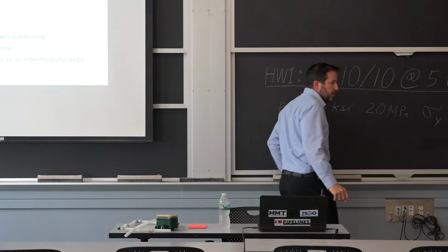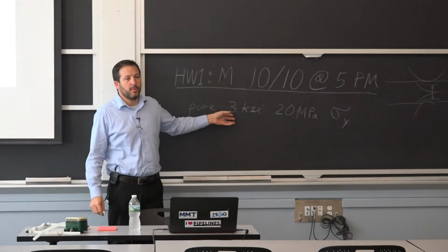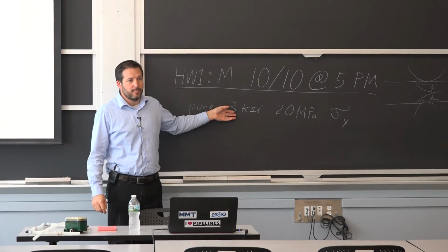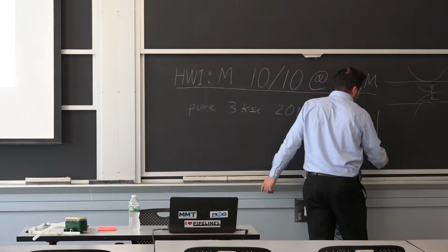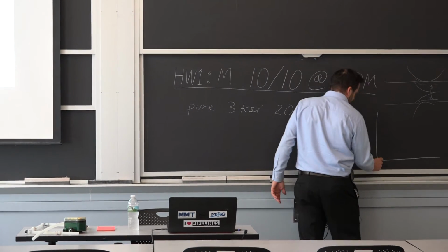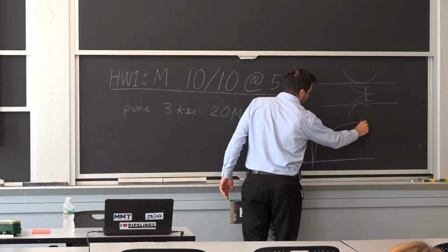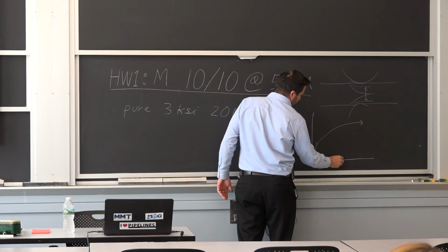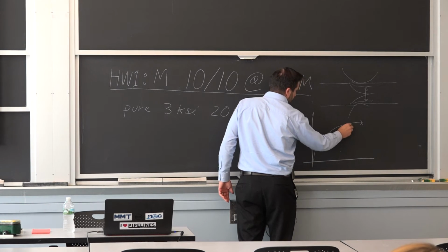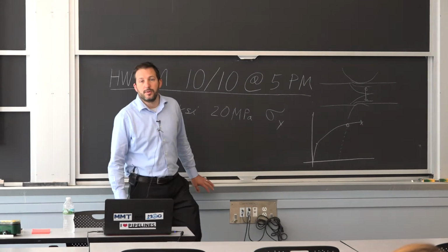Is that enough? No, because there's a lot of tension in the power line. So you try to double or triple that amount, but what it means on the stress strain curve, because you're doing it at ambient temperature, is your aluminum typically will look like this, and then it starts hardening like that up to a strength. What you do with this cold forming of aluminum is you end up getting it to this point, so now it doesn't have as much ductility before it will break.